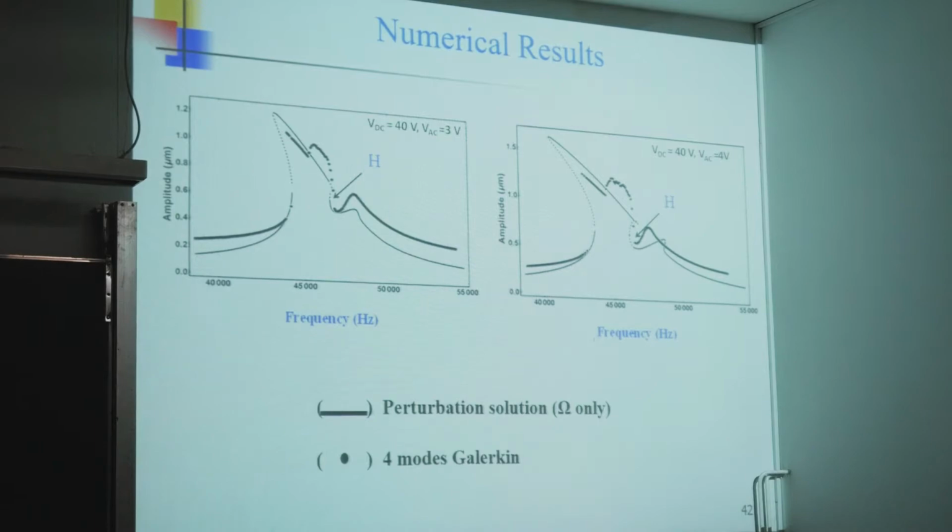First of all, compared with Galerkin. And I have to say something here. It's very unusual to study internal resonance using Galerkin. I think one reason is that with Galerkin, if I don't see this analytical curve, I cannot predict what this is. If someone gives me this, I will tell the student, this is junk. But now, because we know ahead of time that there is something here and there is a half bifurcation, we accept the results from Galerkin. So again, I want to emphasize that I don't think Galerkin will replace the analytical techniques of perturbations. Now we do this because we know. We just want to verify the convergence and so on.